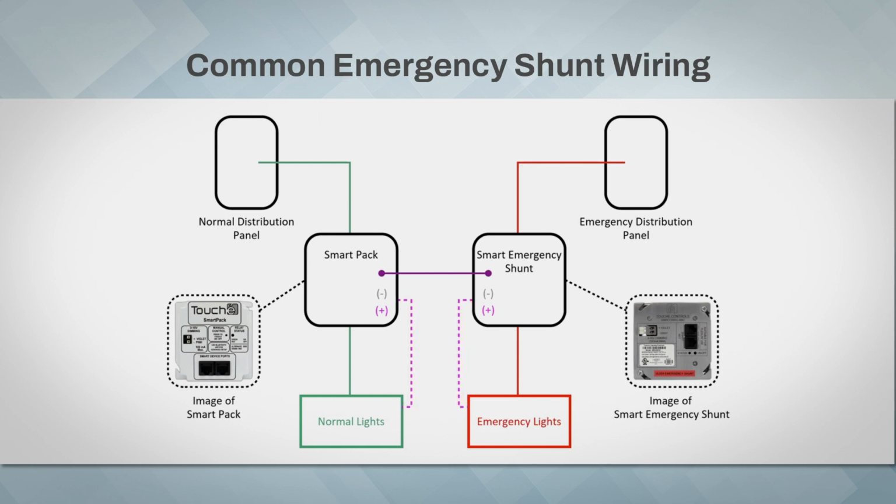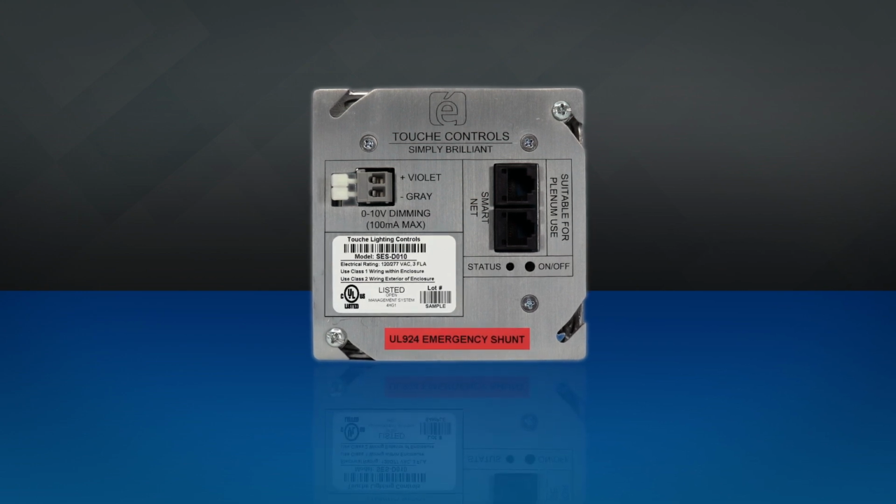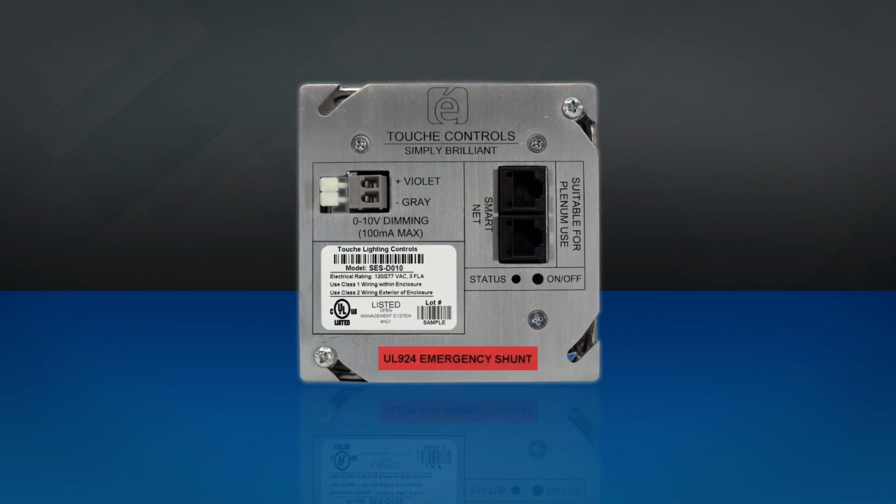Using the smart emergency shunt module eliminates any confusing wiring connections and the need to bring 2 power sources to one device. Under normal operation, when the smart pack turns the normal lights on and off, it tells the emergency shunt to turn the emergency lights on and off. When the smart pack loses normal power, the smart emergency shunt will automatically turn the emergency fixtures to full bright. Finally, a UL listed emergency shunt that is easier to design, understand, and wire.